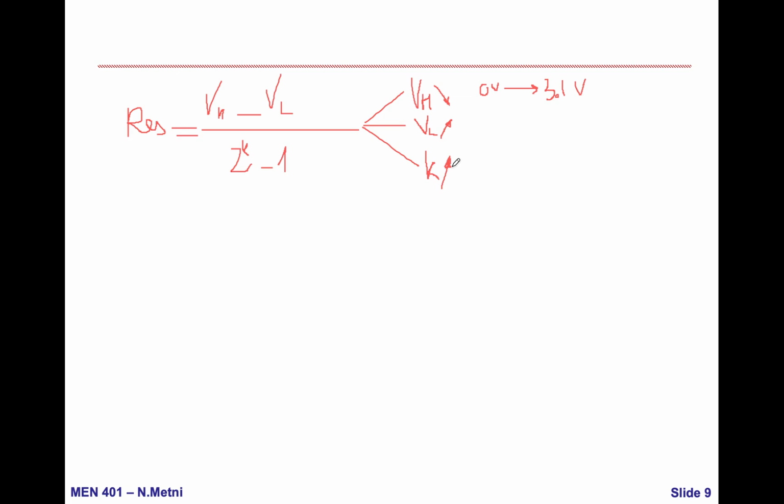Which of these 3 options can be applied in real life on the Arduino? First, this cannot be applied since the Arduino is made with a 10-bit A to D converter integrated in it. So I cannot change k. Generally, practically, most of the sensors have ground as reference and then go up.